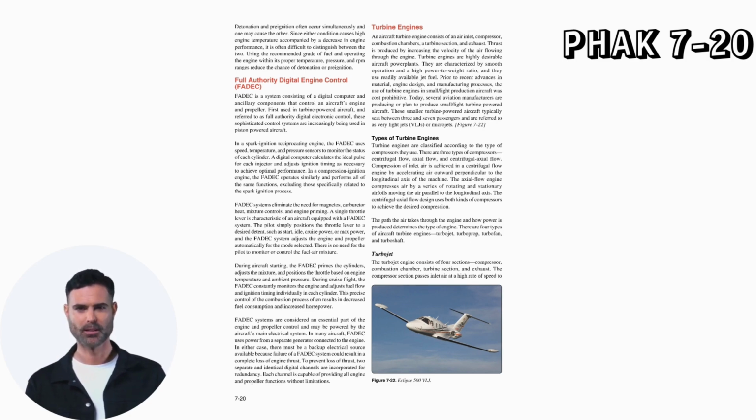During aircraft starting, the FADEC primes the cylinders, adjusts the mixture, and positions the throttle based on engine temperature and ambient pressure. During cruise flight, the FADEC constantly monitors the engine and adjusts fuel flow and ignition timing individually in each cylinder. This precise control of the combustion process often results in decreased fuel consumption and increased horsepower.